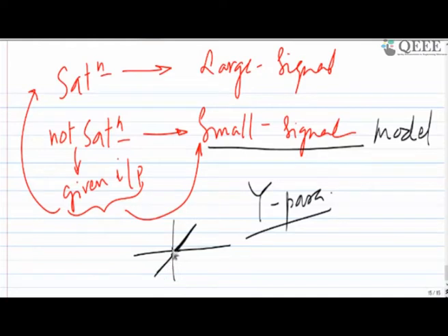crossing from zero. So there is some graphic error, but assume that it's crossing from zero and it's getting saturated. So it's linear only here, not here. I'm not talking about this part of the characteristic. I'm only talking about this part where your input and output have some slope, and that slope decides the gain. And if that is the case, we are calling that region the small signal region.